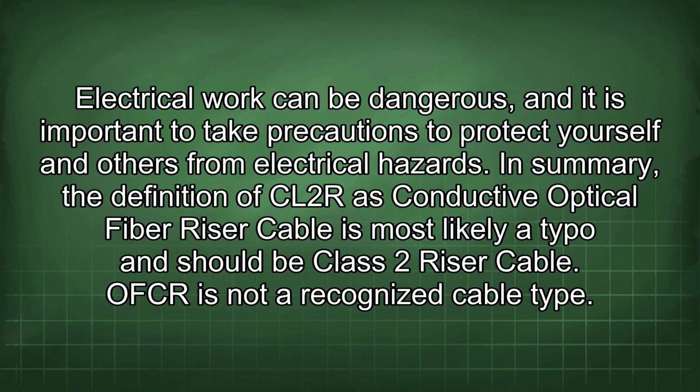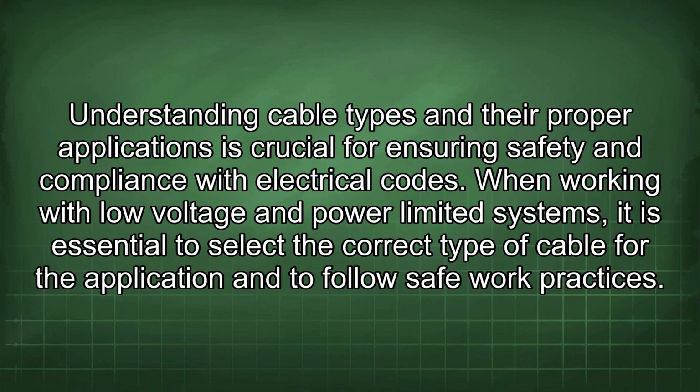In summary, the definition of CL2R as conductive optical fiber riser cable is most likely a typo and should be Class 2 riser cable. OFCR is not a recognized cable type. Understanding cable types and their proper applications is crucial for ensuring safety and compliance with electrical codes. When working with low voltage and power limited systems, it is essential to select the correct type of cable for the application and to follow safe work practices.